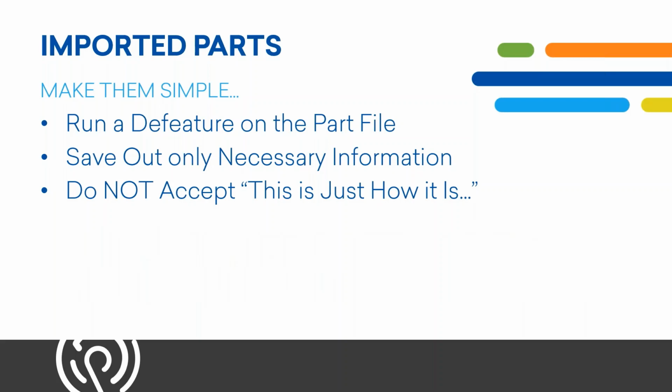Finally, if you're working with imported parts like a McMaster part, those usually are fully featured items. So that's something where you would rather take the time to reduce the complexity, defeature those parts, defeature those assemblies, and reduce your graphical load, sometimes even the file size.